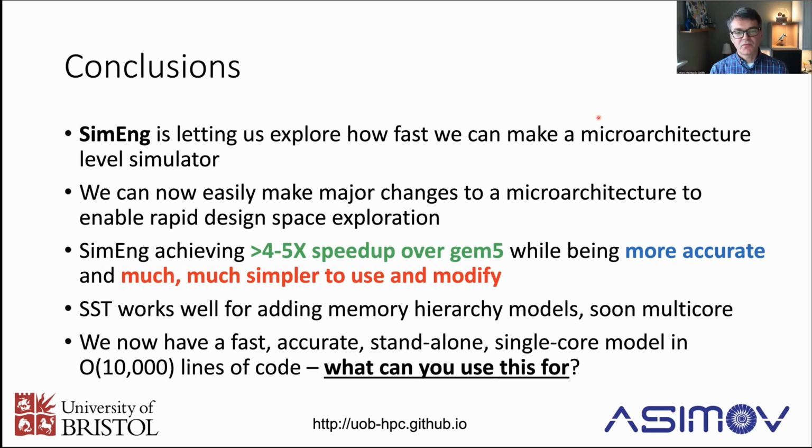No, that's right. We don't have to model bitwise how you do a floating point operation. We can just use a floating point operation from the host. But we are modeling that a floating point unit has a reservation station, and how big that is. So we do go down to quite a low level of detail. But once you get to the fundamental operations, integer operations, floating point, that just becomes a floating point add or an integer multiply on the host.